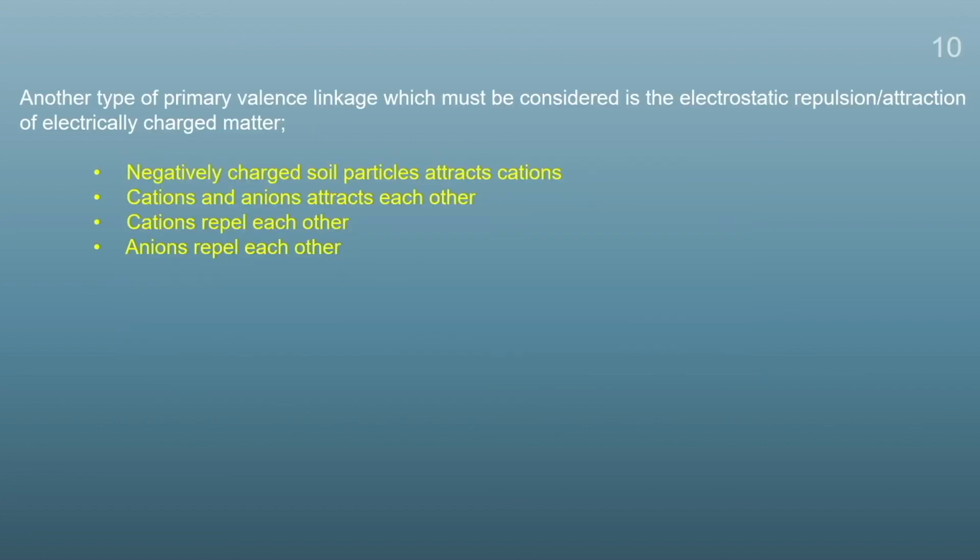Apart from this bonding, there are other linkages between the particles and the ions, which can be either positive or negative, that means either repulsive or attractive. There will be forces of attraction between the negatively charged soil particles and cations. So, this will be an attractive force. Similarly, there will be attractive forces between the cations and anions. There will be a repulsive force between the cations, and a repulsive force between the anions.